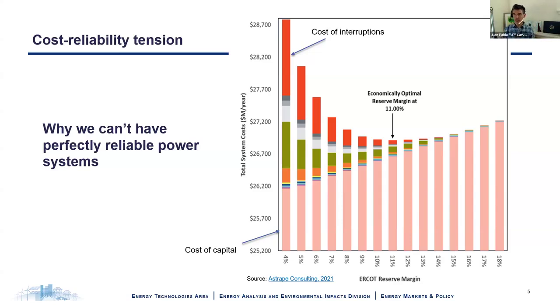A microgrid operates a little bit in the same way. If I have too big of a microgrid, it's very expensive, right? If I have too small of a microgrid, I might not meet load at all times. Your home battery, for people that have battery systems at home, also has a reserve margin, where the battery will go down to a certain level, sometimes for technical reasons, but you can manipulate that if your variable load is too high to ensure that you have a reserve in case an interruption hits.